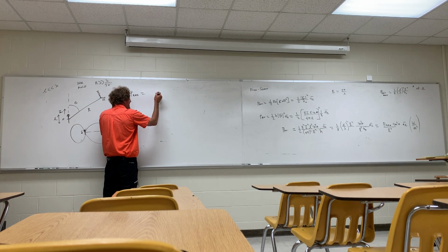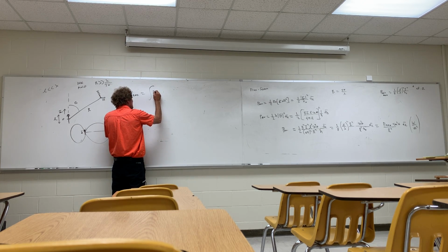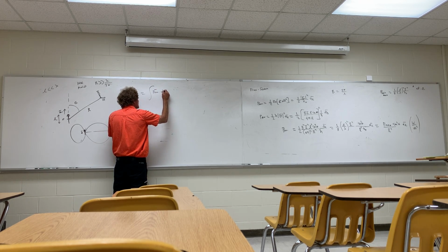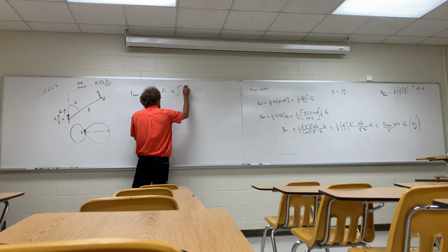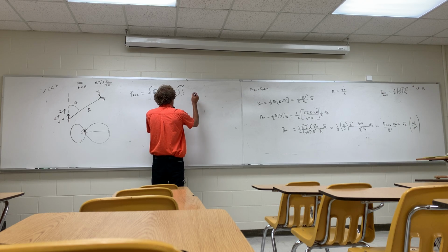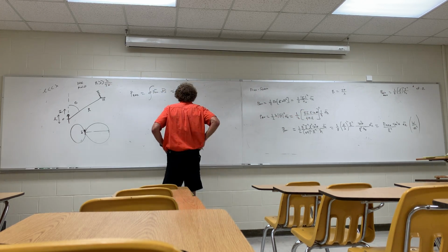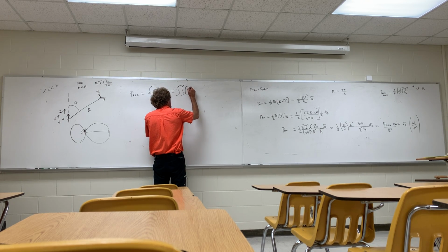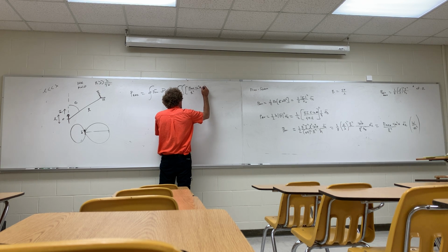We simply go ahead and integrate the power density, called P av, and that's a vector, and we're going to integrate it over the entire surface. This would be a closed integral. So what that boils down to is a double integral of the power density, and I'm going to use just that P max business over there. So it's going to be P max over R squared, and then it's times sine squared of theta, a R,